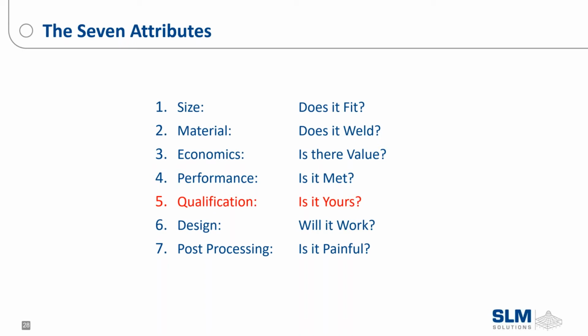Densities. We can have 99.8% density. We can improve that; we have reached 100% density. It's just the amount of control of the process that goes in, and also the application needed. Does it need to be as dense as we can make it, or in other applications, sometimes less dense? In fact, even porous material can be made for certain things such as replacement of sintered filters.